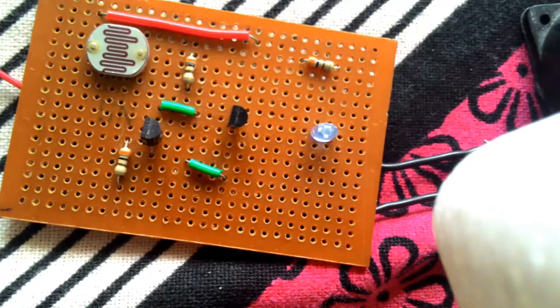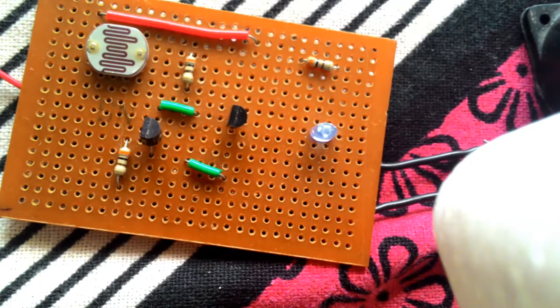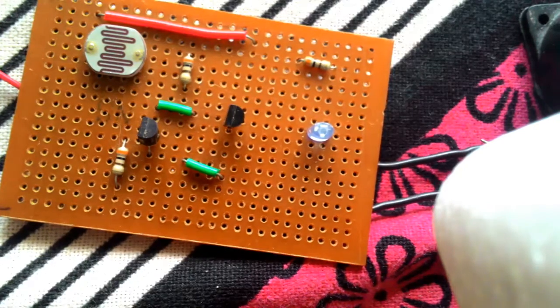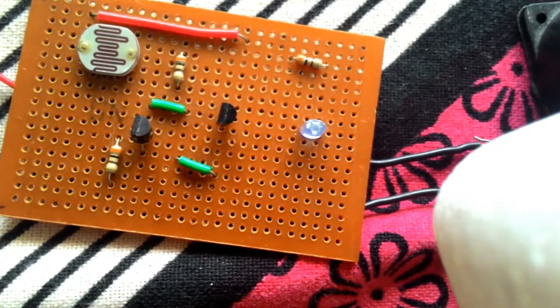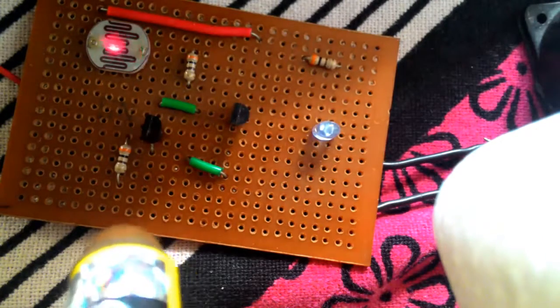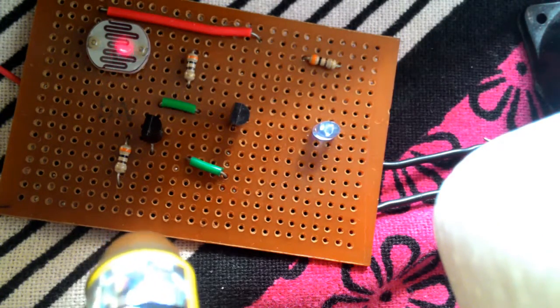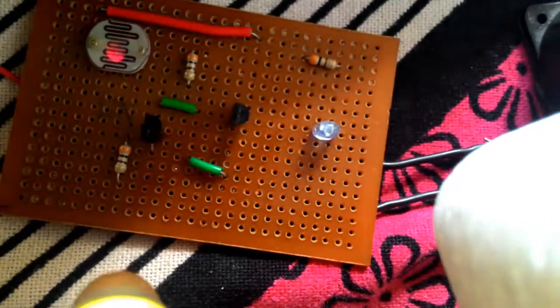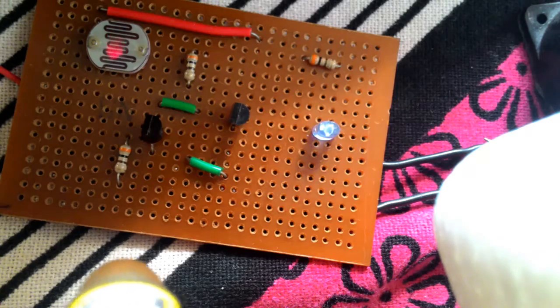Now, how to provide security to our home using the laser. Based on this circuit, we can decide which place to use it. Let's show how it works when laser light is incident on the LDR at night time. The LED is on at night time. Let's see when the laser is not placed on the LDR, and when it is placed on the LDR. When the light is off, the LED is automatically on. When light is incident on the LDR, the LED is off.